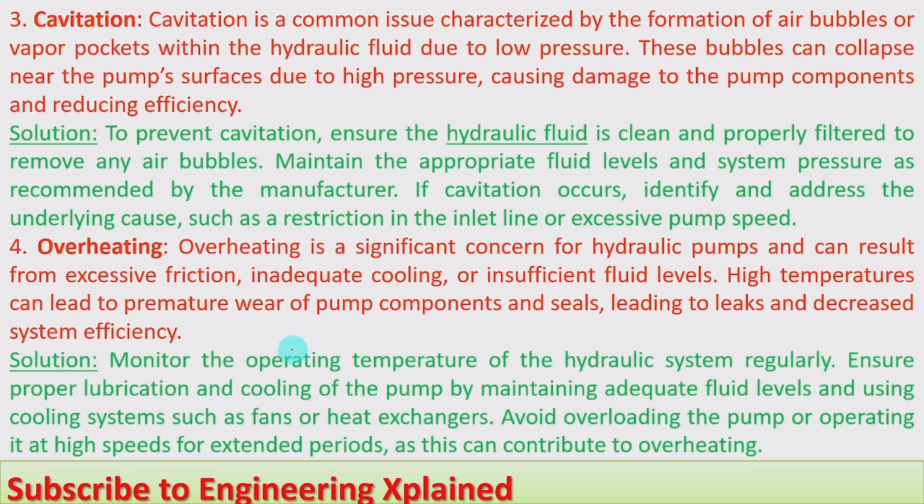And for the solution for this, monitor the operating temperature of the hydraulic system regularly, and ensure proper lubrication and cooling of the pump by maintaining adequate fluid levels and using cooling systems such as fans or heat exchangers. Avoid overloading the pump or operating it at high speeds for extended periods, as this can contribute to overheating. For a longer duration, the pump cannot be used. Then the level, cooling, all these things should be monitored in the system.